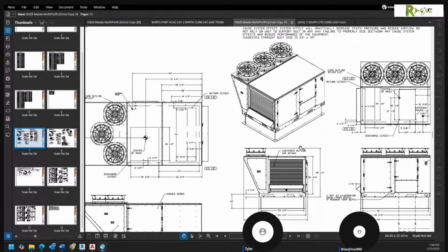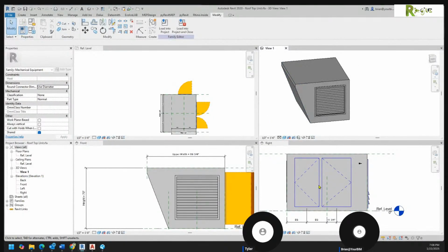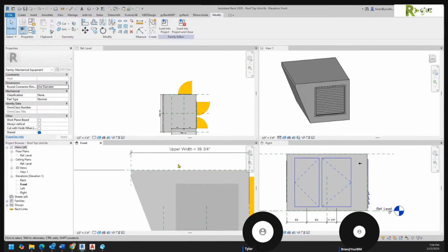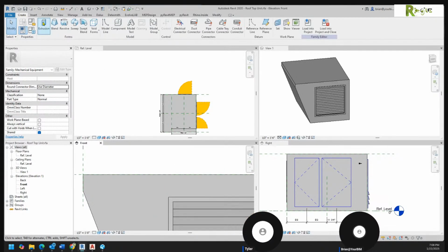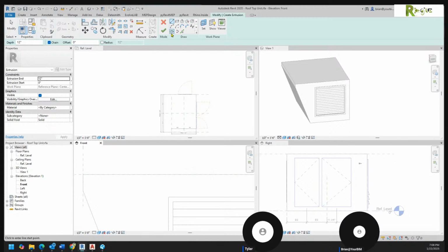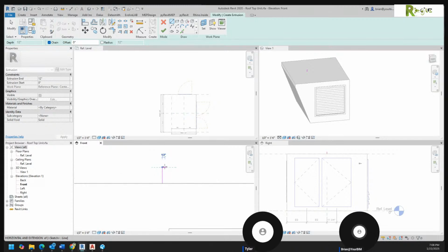All right. So how do we do that? That's just going to be a simple extrusion in this view, and it's pretty much lined up right about in here. So if I just went in and said create an extrusion, notice how I don't want to draw from nowhere. I want to come from the reference plane and come out. Then I can make that thing 3 inches. Now I need to zoom in just a little bit to be able to snap to 1/4 or 1/2.